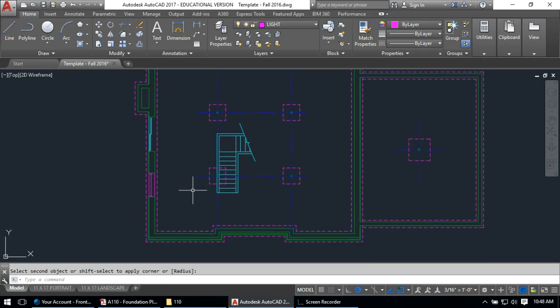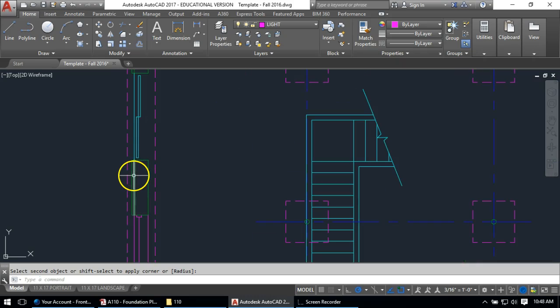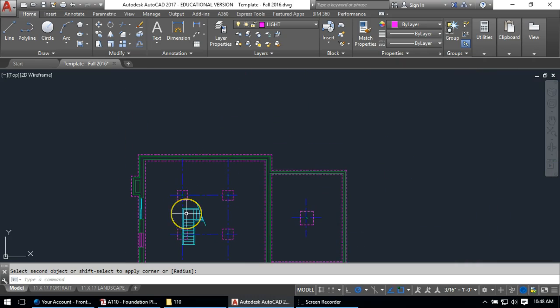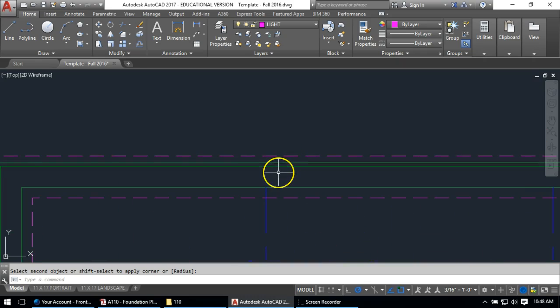And as for basic drawing stuff, the last thing that I'm going to do is review hatches, which are those little speckles inside the foundation and the sort of lines that we see inside the insulation, inside the brick wall. And I actually just noticed a couple more lines that I should draw, which is the pocket for what presumably will be some framing members that go on top of these columns. And we see the note that they're 6 inches deep by 8 inches wide, typical.